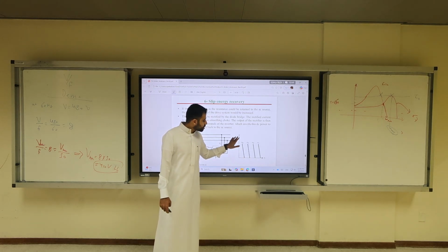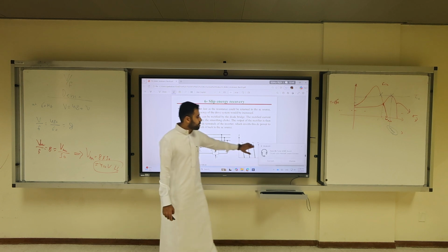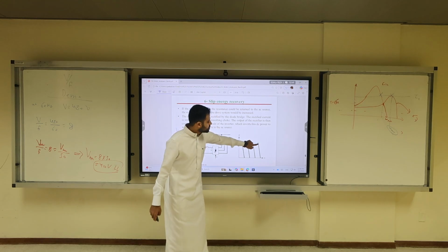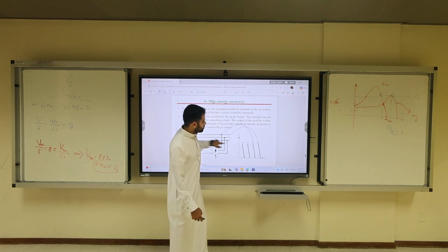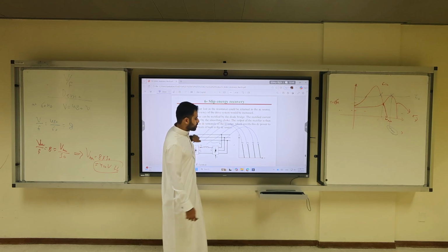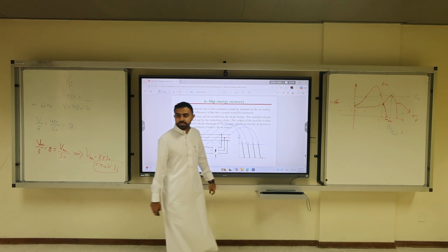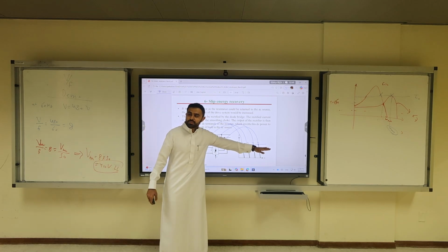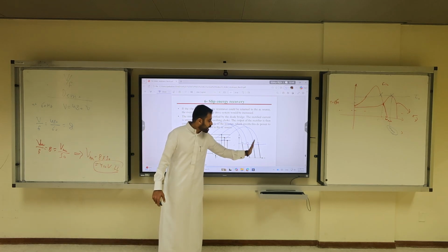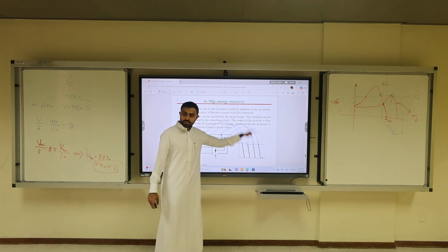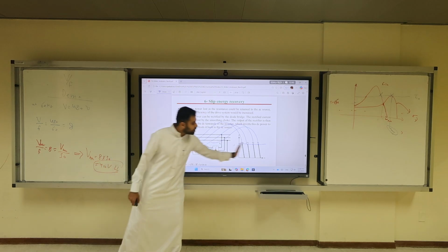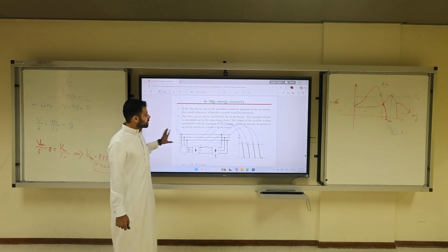Now, if you change alpha 1, alpha 2, alpha 3, you can change the speed, and the torque here actually looks like that. Originally it looks like that. Okay? So your torque is constant. So in slip energy recovery, you operate in the linear region. Okay? These lines are the linear region of the capability curve of your motors. So if you change the speed, you can shift the energy recovery.